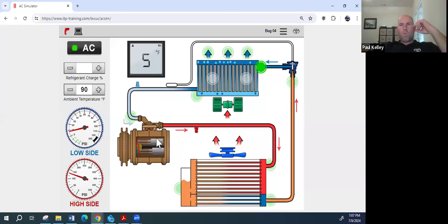But if the compressor's kind of worn out, these little pistons and the little sealing rings, all that stuff are kind of beat, it's like a high mileage engine, it's not going to make that much compression. So it's not going to pump the high side as high. The high side right there is not that high. I like that. That might be a compressor on economy mode or a compressor that's kind of worn out. But the low, no, a worn out compressor doesn't draw the low side below 10. That's like totally weird. How could the low side be almost into a suction state?